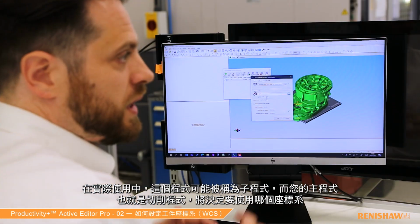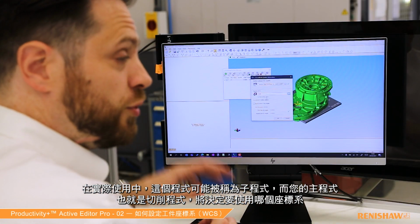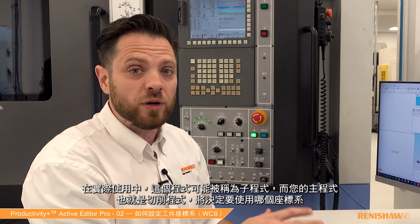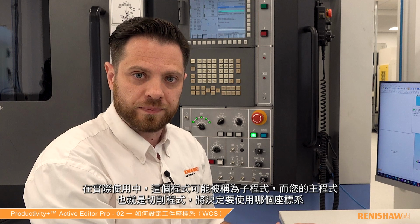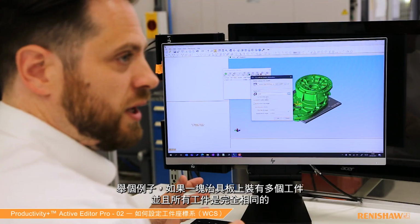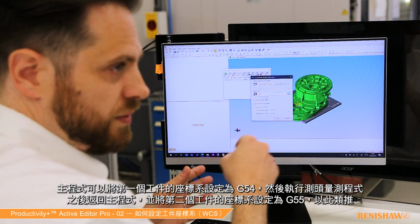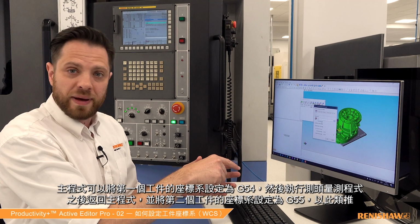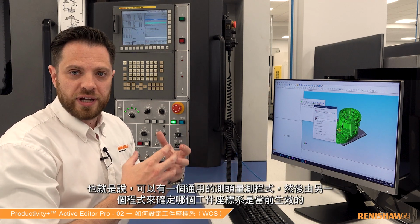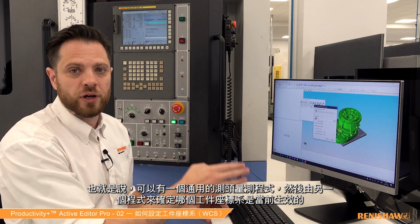Now it might be that this program is being called as a sub-program, and maybe your main program, your cutting program, might be the one that's going to determine which coordinate system we're working in. An example of that could be if you've got a plate made up of multiple parts, all identical, the main program might set the first one as G54, then you run your probing program, come back to your main program, set the second one as G55, and so on. That means you can have a generic probing program and allow a different program to determine which work coordinate system is active.